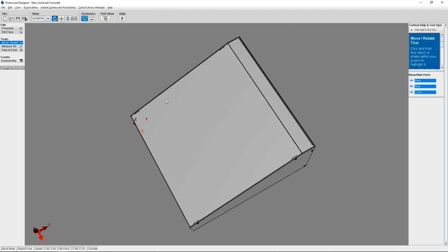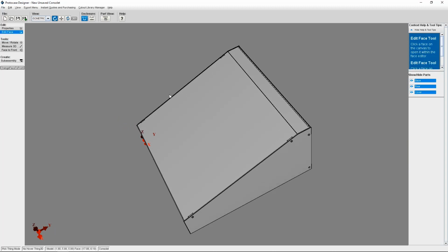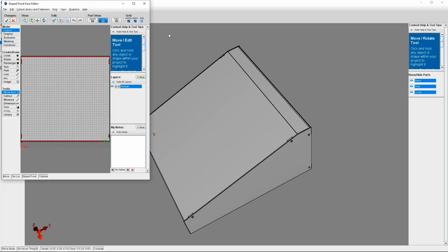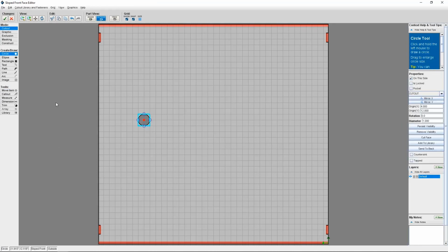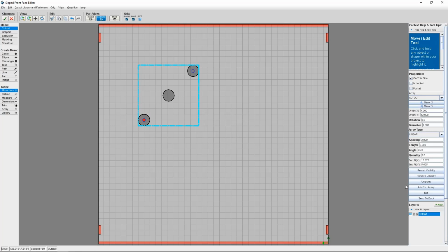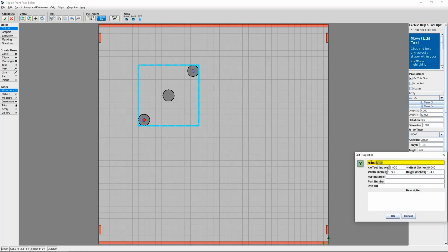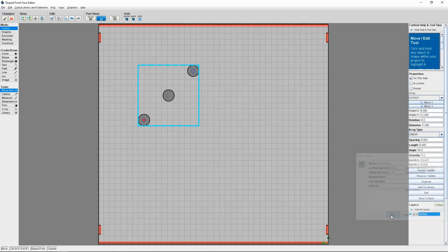Sometimes customers will create a note to indicate what connector corresponds to a particular custom cutout they've created. You can do this if you'd like, but it's more efficient to name the cutout itself with a connector name and add it to the cutout library. So in this example, I'm creating a custom grouping of cutouts using the Array tool, then saving it as a cutout in my personal library. I don't need to add a note to this cutout because it's already labeled in my cutout library.